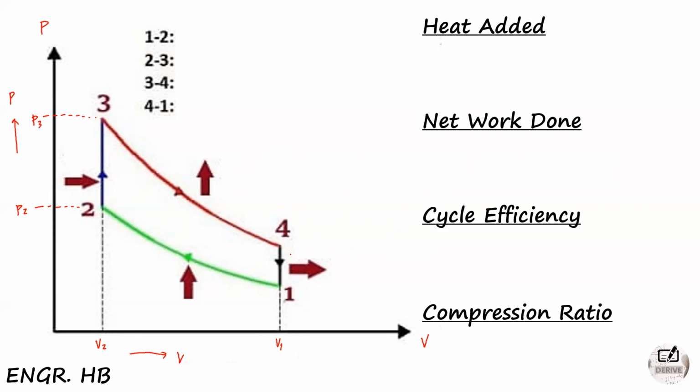Okay? So ano muna yung 1 and 2? So 1 to 2, the process is called the isentropic compression. So obviously, we are all familiar in this kind of curve pagdating sa PV diagram. Tatlo lang naman ang curve niyan. It's either isentropic, constant pressure kapag horizontal, and of course constant volume kapag vertical. So this is an isentropic compression, meaning from volume 1, nag-compress ka papuntang volume 2.